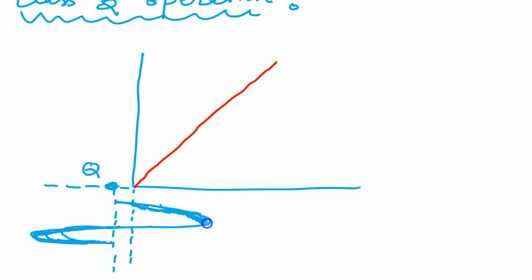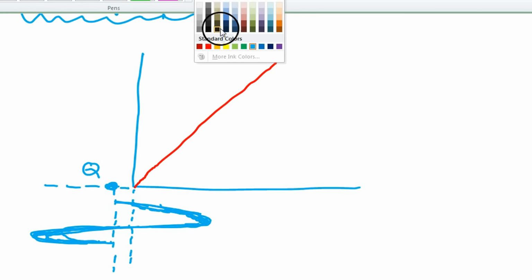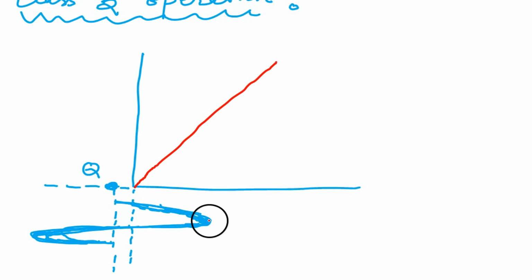As the input signal varies, exactly in the same way the base voltage varies. But you know, some part of the base voltage will not respond to the collector current because the Q point is just near the cutoff. So we see how much part of the base signal is converted to the collector current.